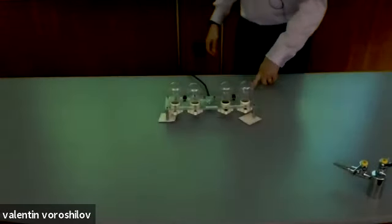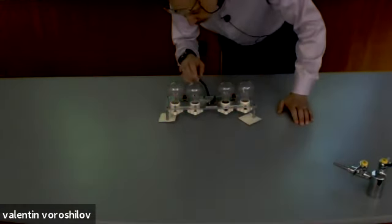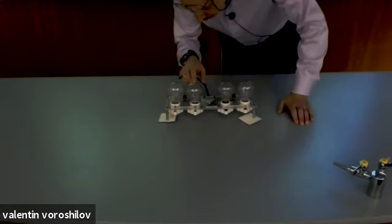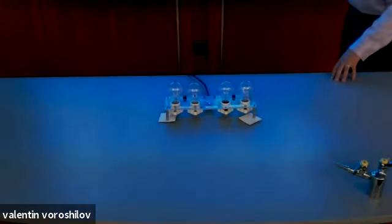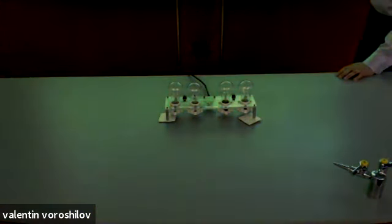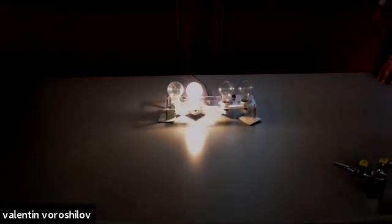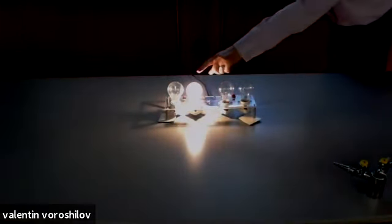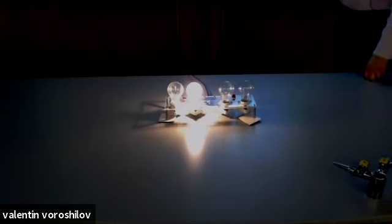Okay. But here we've got the same situation, 40, 100. But now they are connected in series. You can follow the wire. The black wire goes to this and then to the next bulb, and then it comes back through the switch. And now you can see 40 is much brighter, 100 is barely lighting up.